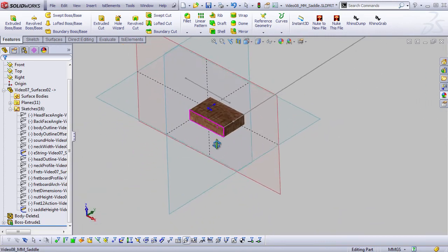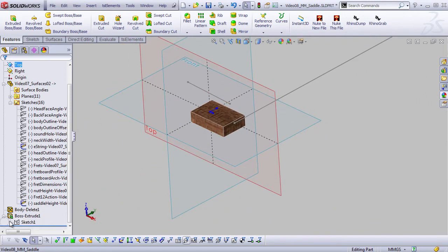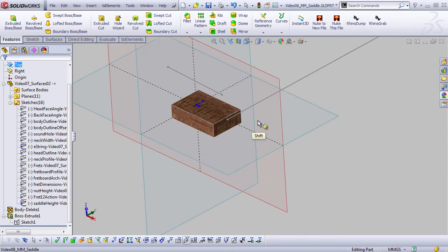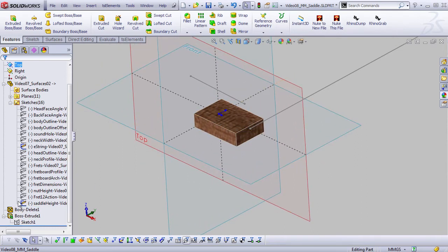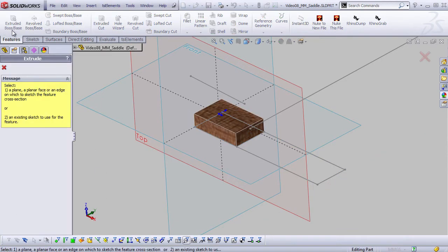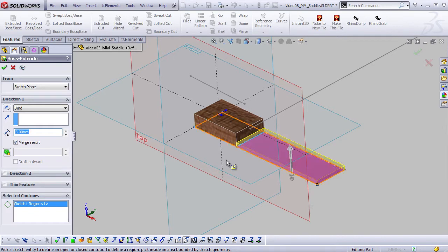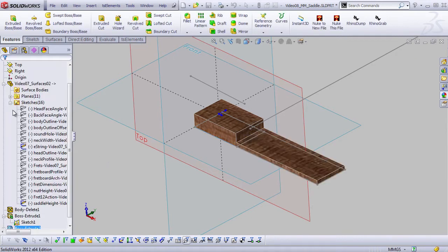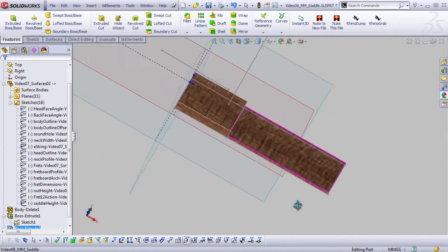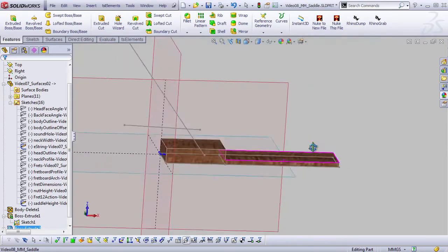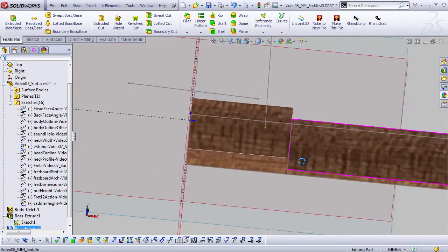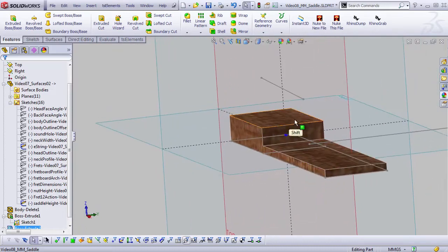And also, there's more to this, though. Let's re-show that same sketch. You can actually reuse sketches in Solidworks. So over here in the Extrude feature, we've absorbed our sketch. But I can show it again, and then run the Extrude tool again, select that same sketch, and just use this other section. And we're just not going to come up quite so high. This time we're going to come up 3 millimeters, let's say. Click OK. And we're left with a basic bridge shape. And we can do more to sculpt that shape in a little while. First, let's get the dimensions right.